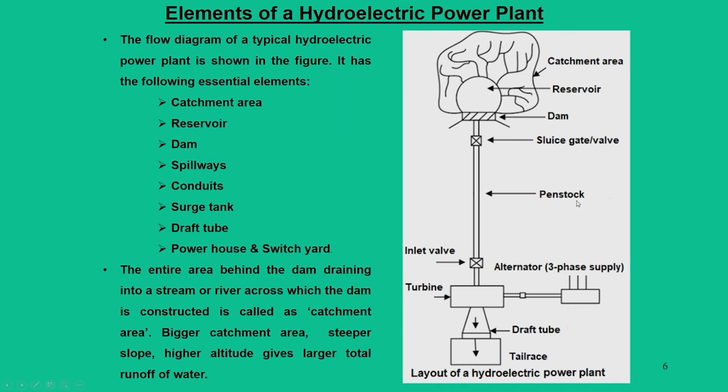It is simply the water pipes. Then through this penstock it goes to the turbine end. Here at the turbine end we harness the power, and then it can be integrated with an alternator, for which electric power generation is possible. Then the discharged water goes through the tail race. Tail race is another kind of catchment area where water is discharged. One most important thing is that the water has to pass through a draft tube, and this draft tube is a very significant component of this power plant unit, because it creates a necessary controlled pressure difference upstream and downstream, and water has to go in a smooth manner to the tail race, so that it does not incur many hydraulic losses.